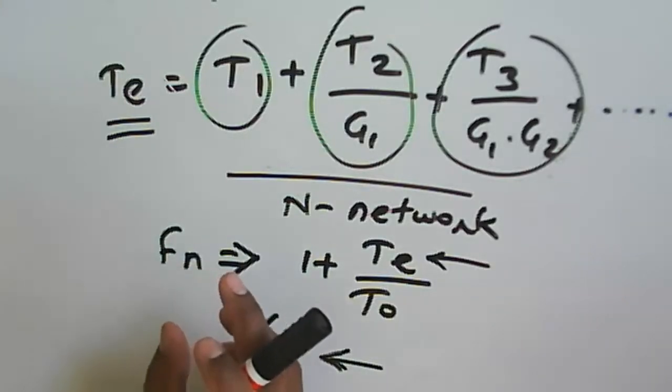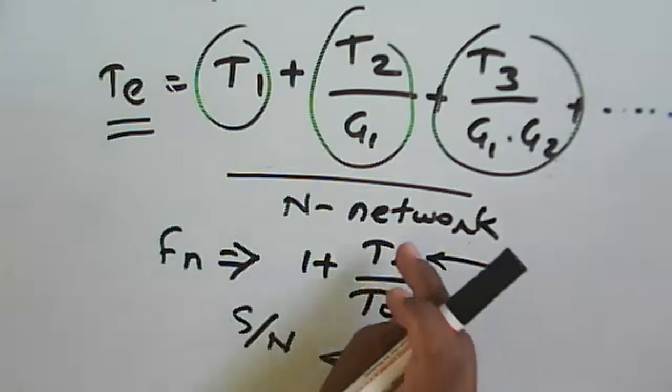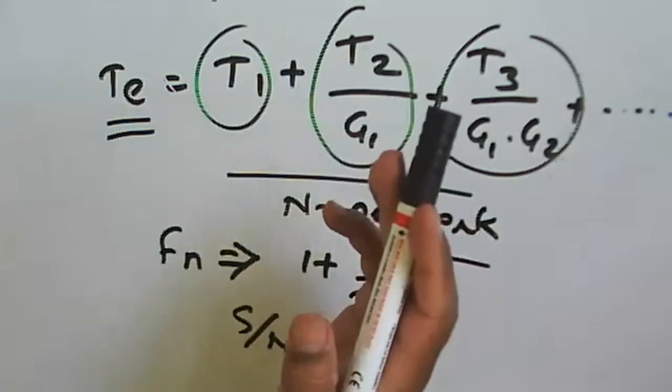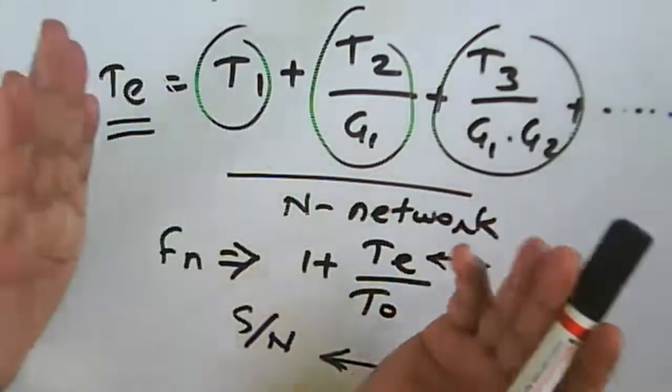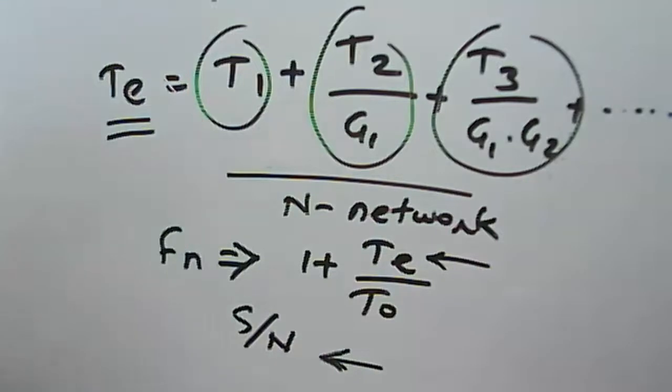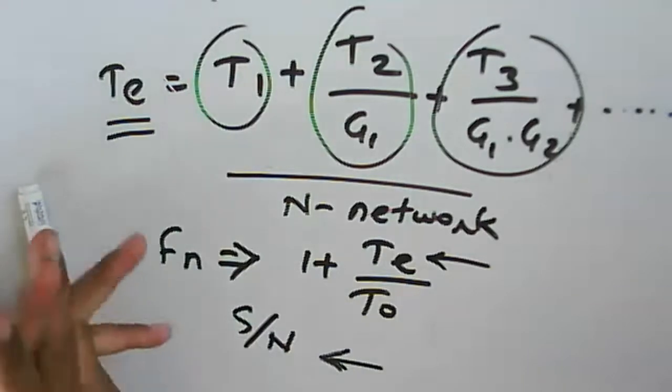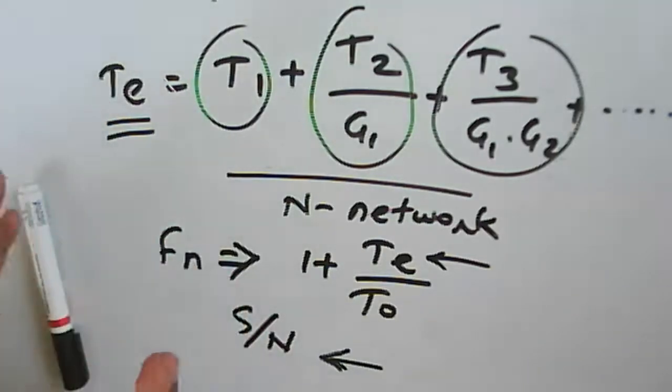Noise figure can be measured in terms of whatever system components we are using. Suppose we consider the receiver component, say a mixer, and the noise generated by it will be reduced. What will be the overall system noise temperature? So we can improve the signal to noise ratio by minimizing the noise of the components we are considering. With this, we stop here.